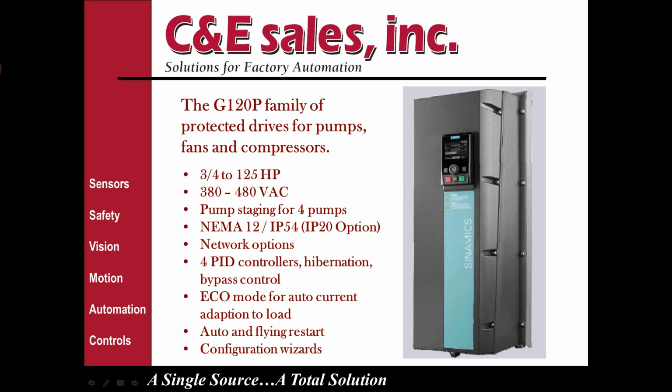They are set up with 4 PID controllers, and you can also do pump staging up to 4 pumps with this, so that you can configure the drives to share the load or to sequence through pumps so that you spread wear of each pump over the multiple pumps.